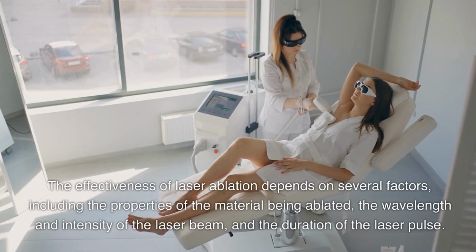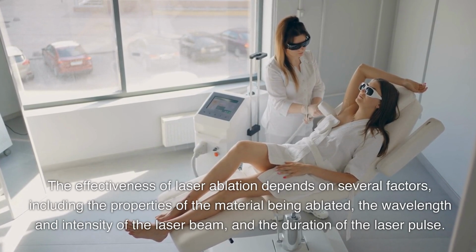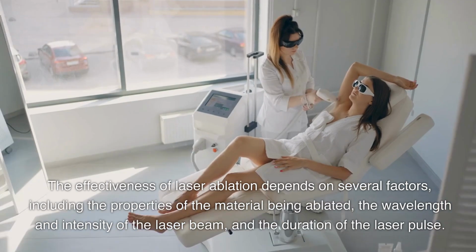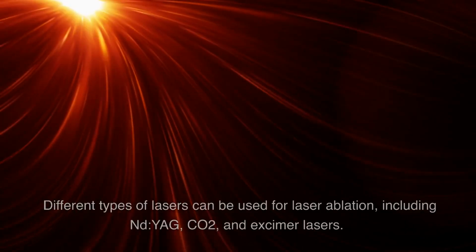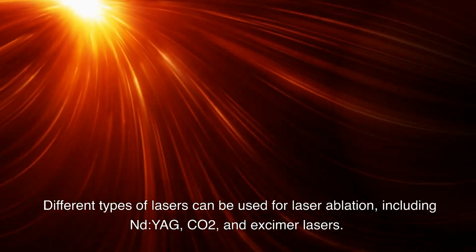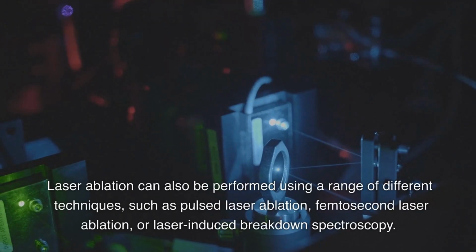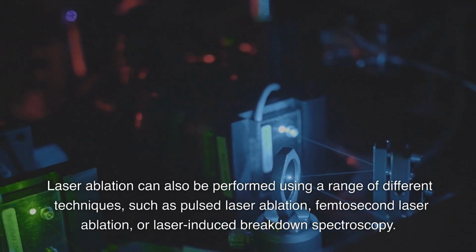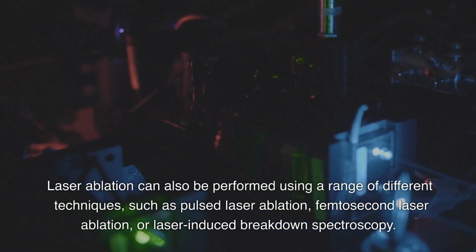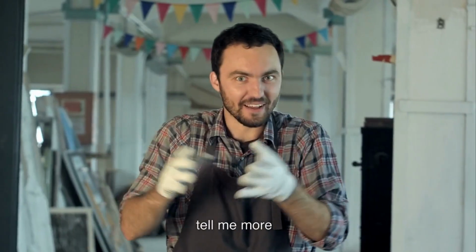The effectiveness of laser ablation depends on several factors, including the properties of the material being ablated, the wavelength and intensity of the laser beam, and the duration of the laser pulse. Different types of lasers can be used for laser ablation, including ND-YAG, CO2, and excimer lasers. Laser ablation can also be performed using a range of different techniques, such as pulsed laser ablation, femtosecond laser ablation, or laser-induced breakdown spectroscopy. Tell me more.